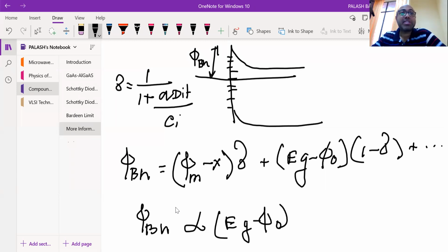The semiconductor band gap and the neutral point of your interface states, right? That we have seen. So that means if you have defects, you are going to have a φn of around 0.8 or 0.9 electron volt, meaning you have that big a barrier, and getting ohmic contact out of this barrier becomes a problem. So you will always have a huge contact resistance, and you have a loss of voltage across this contact resistance. So this is a problem.